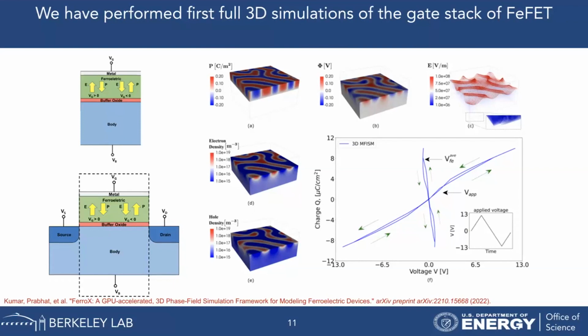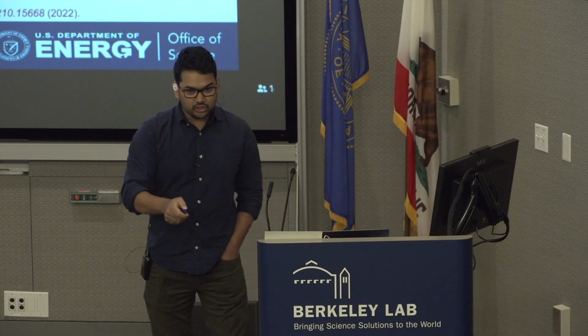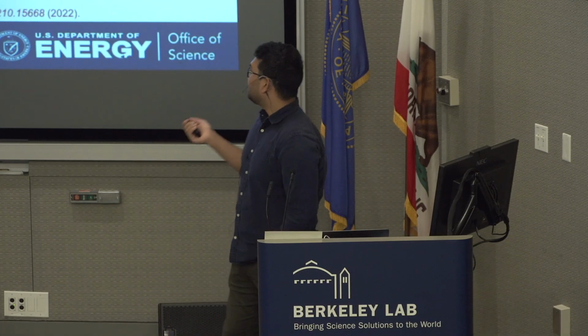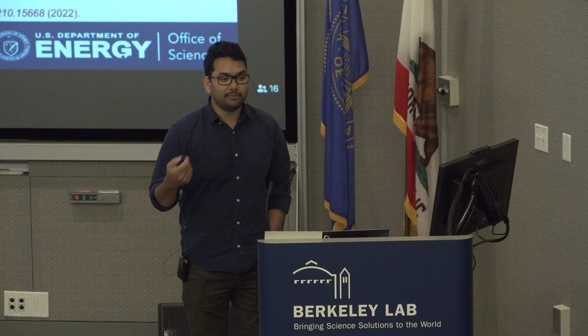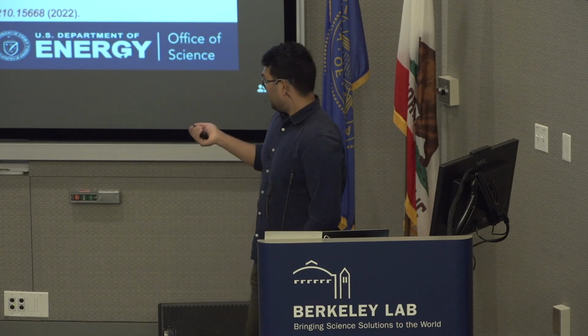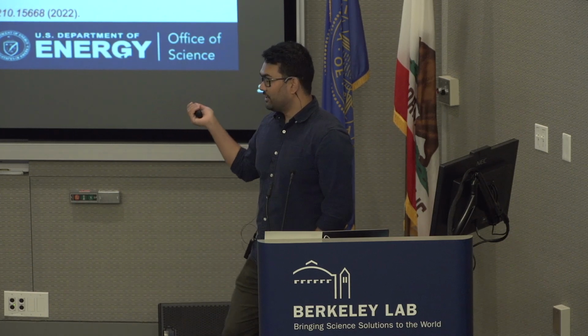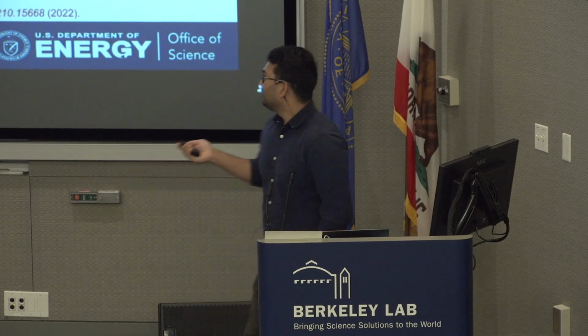We also characterized, quantified the effect of doing this simulation in either 2D or full 3D, and we concluded that 2D simulations overestimate the effect of negative capacitance. For more details, I welcome you to read our paper, which we submitted a few months ago.